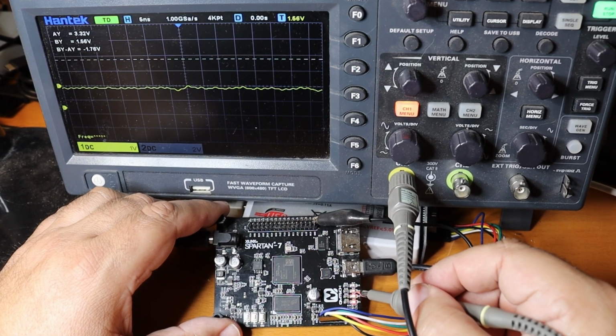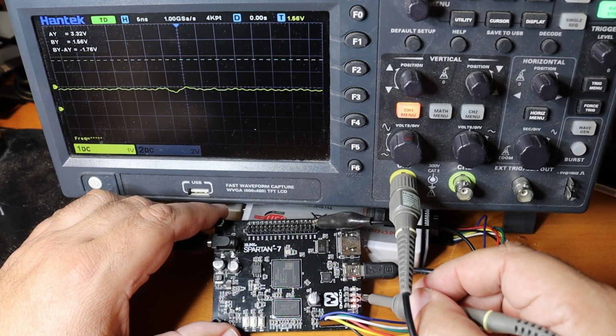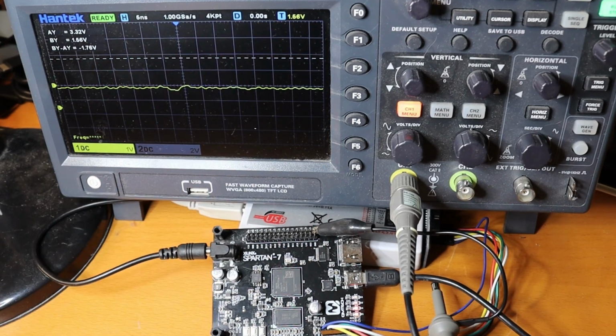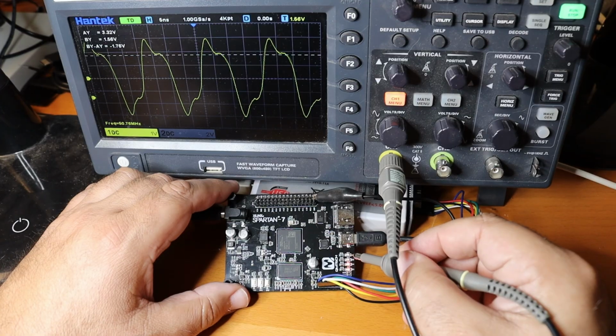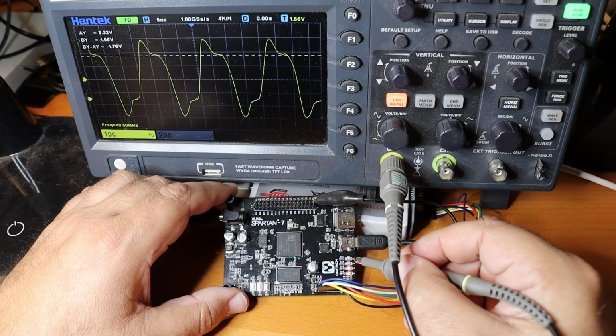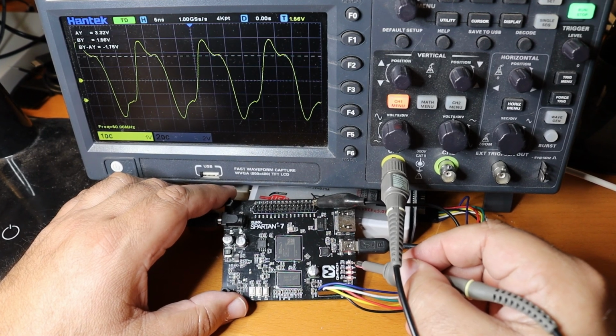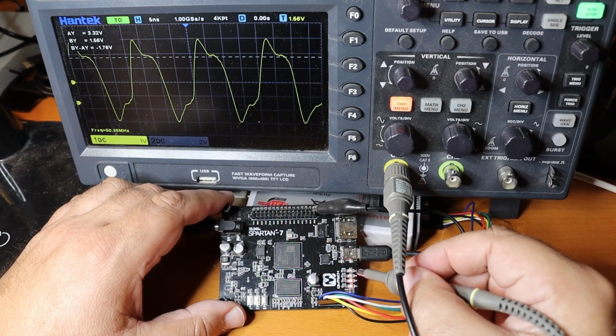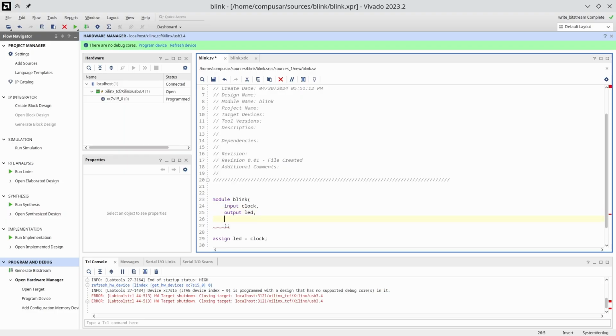In other words, the reason D2 is faintly glowing is because we didn't tell the FPGA what to do with it, so it kind of defaulted to this state. D3, on the other hand, is faintly glowing because the clock is a 50 MHz clock, which is way too fast for us to see blinking. Fixing D2 is easy. We'll just define an output for it.